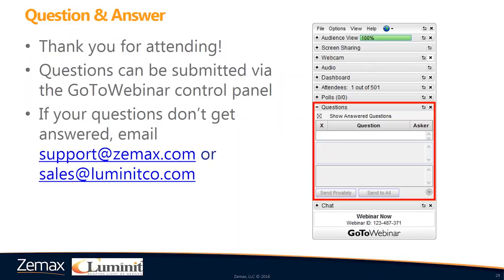All right, next question. Which angles of incidence range work properly? Okay, so as long as you're, let's say, coming in from negative Z to positive Z direction of the object, as the object is in its initial location without prior rotations, it should be fine from anywhere from 0 to almost 90 degrees, as long as you can intercept the rays. Okay, but if you rotate your object, you also have to rotate which ways the rays come in.